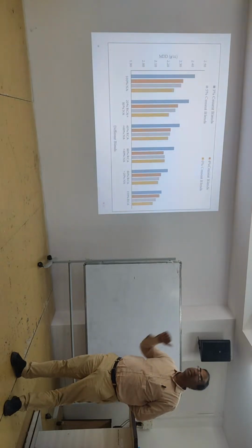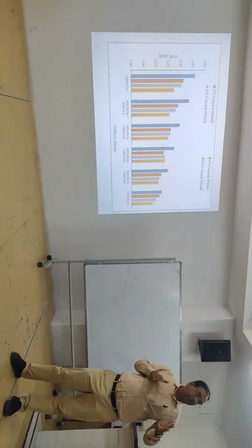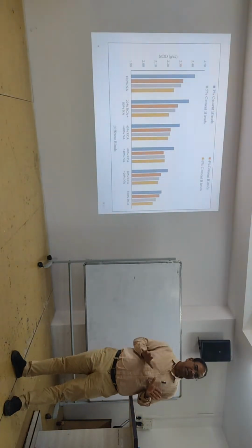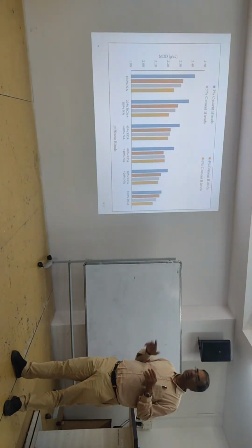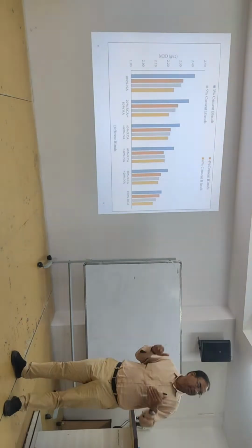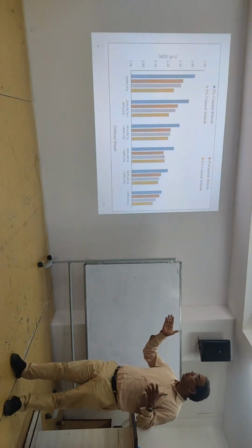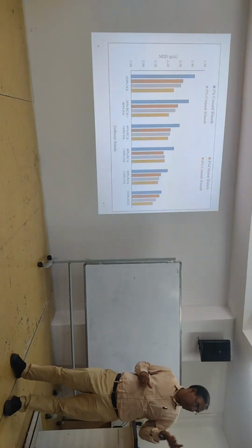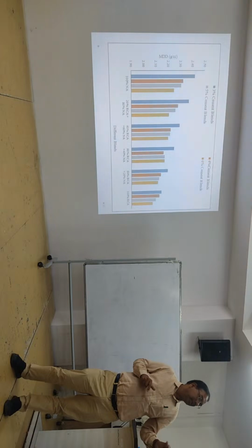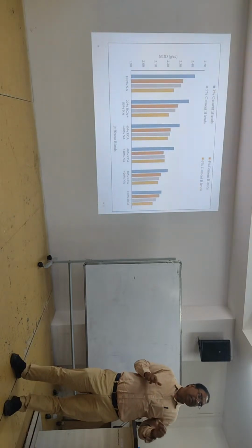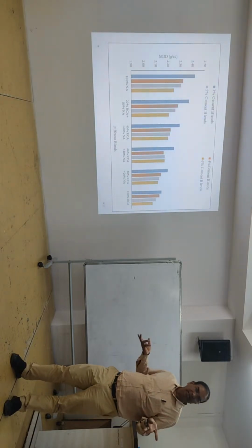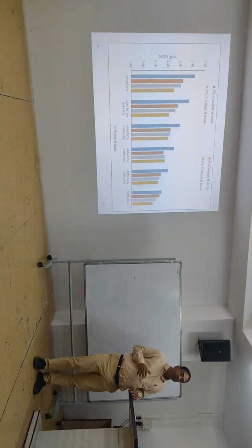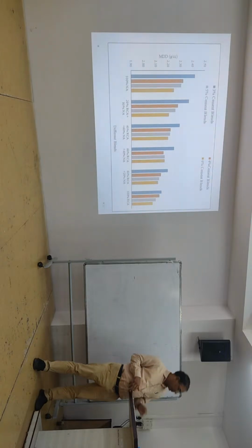So almost both are the same. Even when you add 20% recycled aggregate, you are not getting much difference at any level, just a little bit here and there. As you have seen in the photograph, some brick particles are there. Brick takes a lot of water. If you remove the brick, it will be as good as natural aggregate, but then the cost of the material will increase and nobody will use it. So the brick is there, and that is why we get these results.